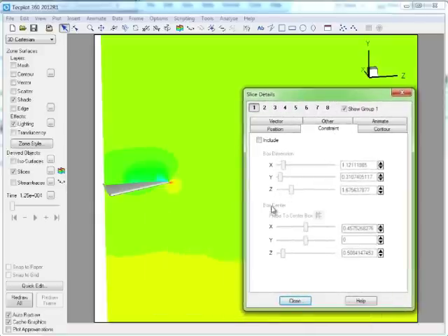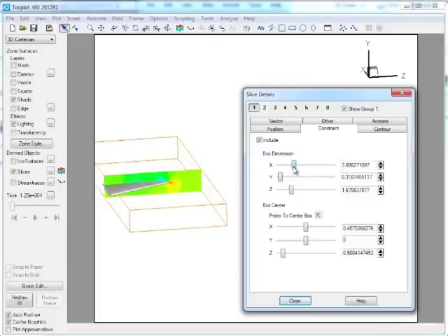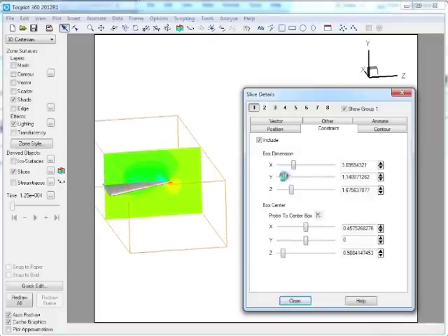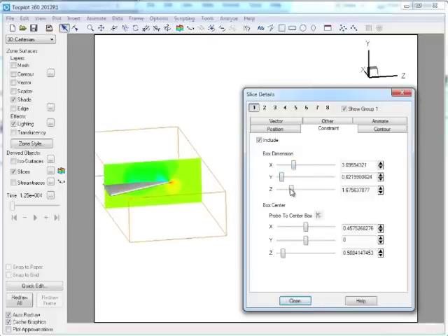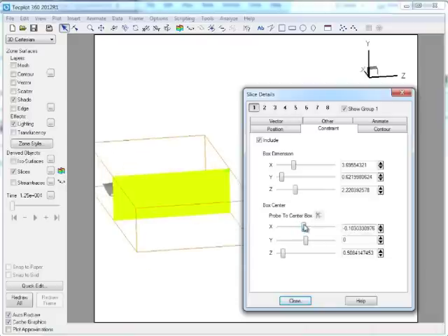Now, often we're more interested in off-body pressures, so we're more interested in really evaluating what's going on near the object of interest. So by using, in this case, what we call slice constraining, we can, in essence, encapsulate an area of interest using a box, and we can move the box where we want in the domain.